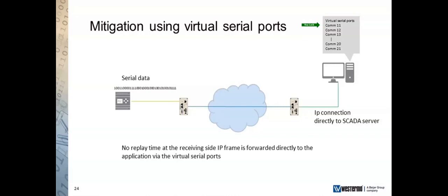So timing has basically been halved, or at least reduced significantly, compared with doing a serial to serial replay. You'll find this is much quicker, much easier, much more flexible than using terminal servers and the like on your systems. Now, here's the animation. The IP packet and serial data is passed straight to the SCADA system and is used by the application right away. So everything transfers in memory.